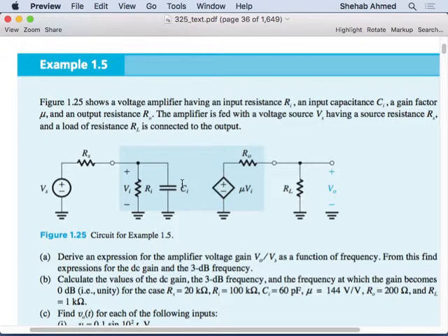A single time constant circuit will always behave like the low pass or high pass filter that we talked about. So the behavior will be exactly the same. The frequency domain plot of the magnitude and the frequency domain plot of the phase of the transfer function will always be the same. It's just that where are the numbers, right? Where will be the corner frequency? Where will the magnitude be at DC, etc., etc.